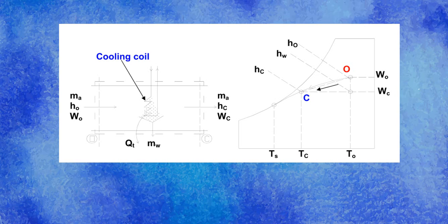Now, you will have the corresponding amount of water here that was condensed in the process. So that's your m sub w, and you have here the final amount of dry air, its enthalpy, and its humidity. If it's depicted on your psychrometric chart, this is your initial state and this is your final state. This is your initial humidity, this is your final humidity, this is your initial enthalpy, this is your final enthalpy, and this is just the enthalpy of the saturated water that was condensed.